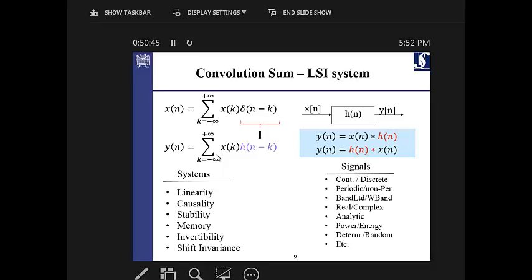Yes? Is it the deconvolution process? That's the deconvolution. Actually, you're deconvolving, and the effect of the system is removed. I think that's a dangerous process, right? Doing deconvolution. I mean, is this the one where we're doing de-blurring kind of stuff? Deconvolution is a more general idea. The basic idea that you can get from deconvolution is, yes, you're getting the inverse of the system, or equalizing the system. Have you heard about equalizers in telecommunication? Yes. Equalizers are actually doing deconvolution. Have you heard about source separation, blind source separation? Blind source separation is nothing but a deconvolution.